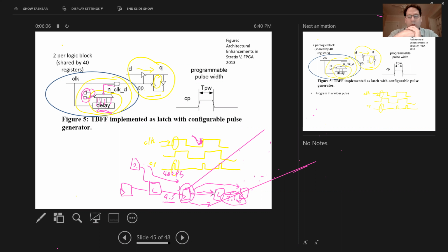Or sometimes you do wind up with 2 clocks in a single logic block. It can be useful occasionally to have that because you've got some clock crossing logic. Like you do actually have 2 different clock domains that are interfacing, and putting those 2 sets of registers in one logic block can be useful. So it does happen sometimes. The more important reason is probably to allow different time borrowing settings for different registers in the same logic block.